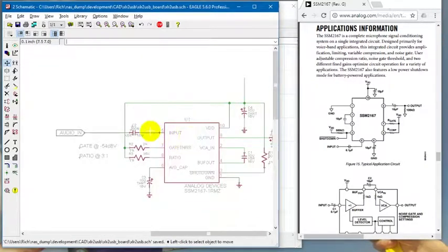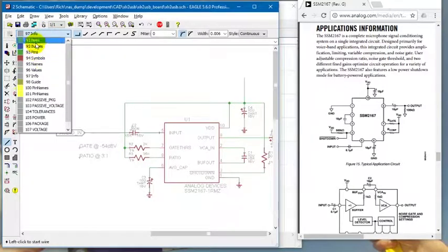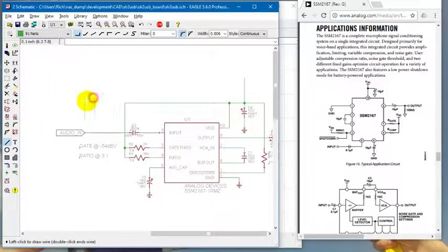And we learned the very most important thing, which is never use wire. Never, just don't even use it. I haven't really found a reason to, unless you want to draw some picture or make a little block diagram. But don't do it. And sure as hell, don't ever put that on. You can do wire and pick a layer, and you could really fake somebody out by doing one of these. Yeah, see, it's don't be this guy. Don't ever do it. Boo on you. Use net. Net is the command to use.